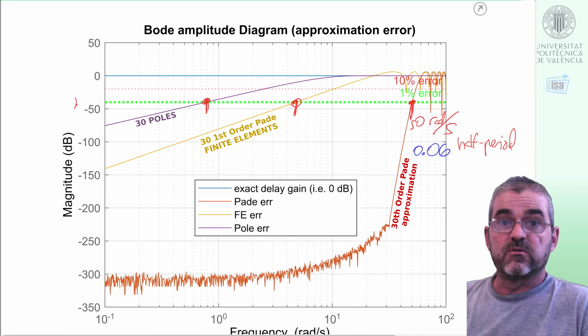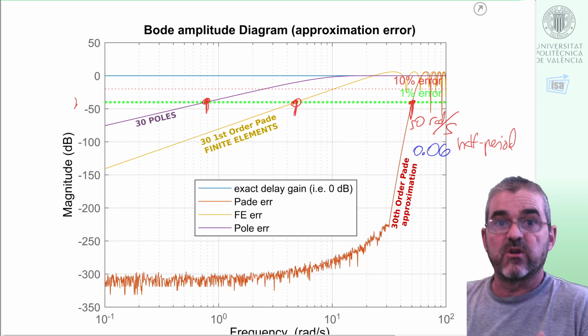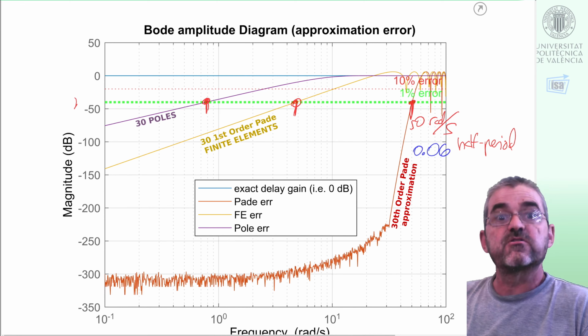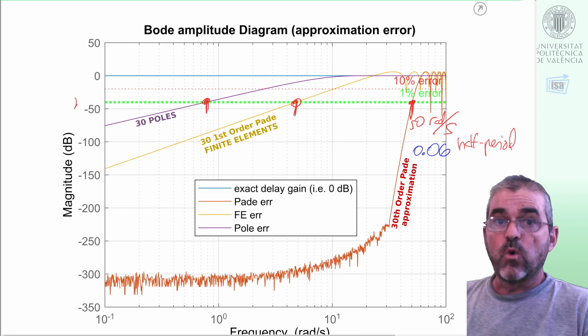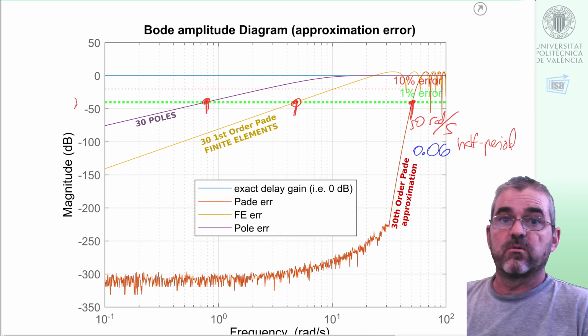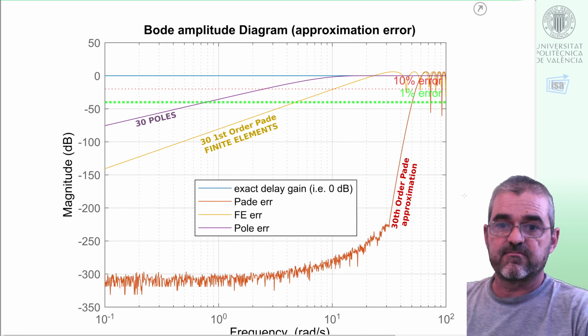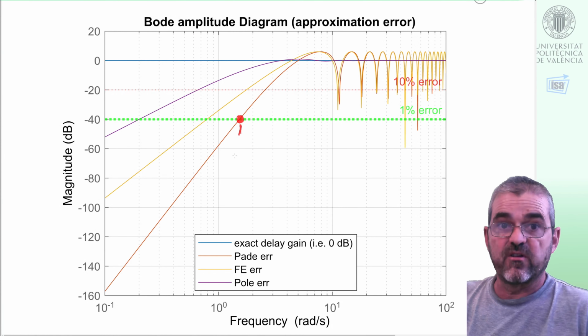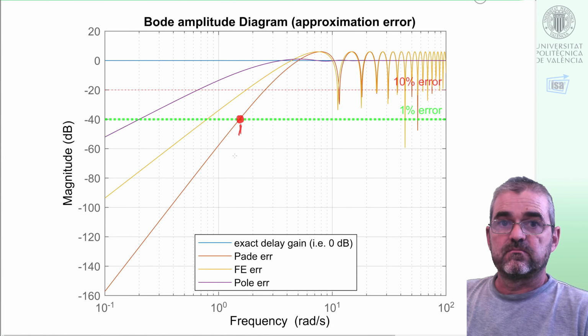and the available computing resources, so that we have reasonable simulation times. It's nonsense asking for a supercomputer to simulate 10 seconds of this pipe and taking 2 months to carry out such a simulation. As I said, in most applications, delay approximations stop at first or second order. I put 2 and compute again if the bandwidth of the applications of the overall system is small enough. Most books will tell you to approximate the delay with a first order Padé and stop worrying about this.